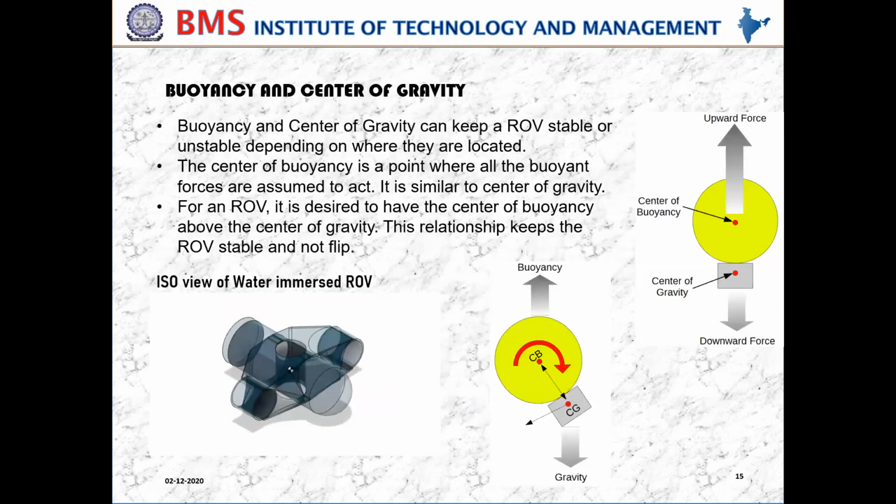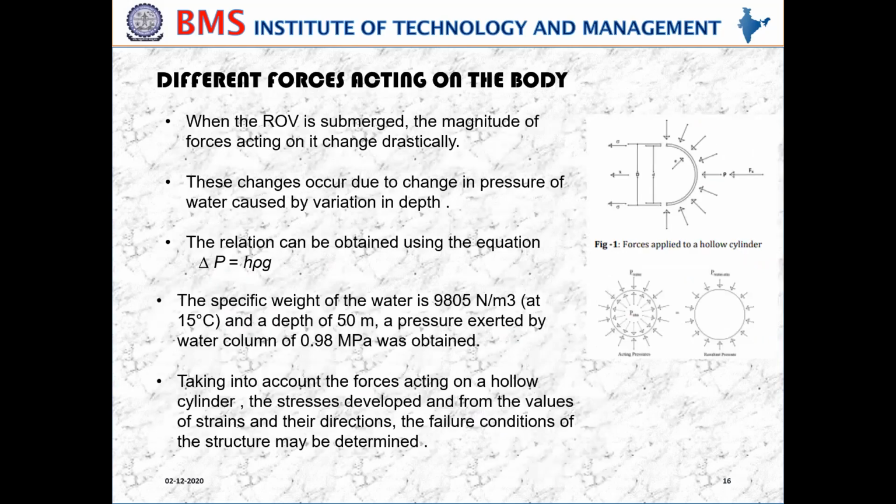And you can see, as shown in the figure, that we have got the science behind how to maintain the stability. So we had to just make sure that the center of buoyancy and center of gravity are very close by, with the center of buoyancy a little higher and the center of gravity a little lower, so as to maintain stability and not produce any torque sideways.